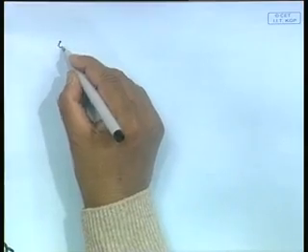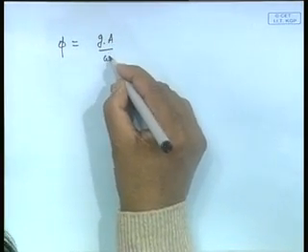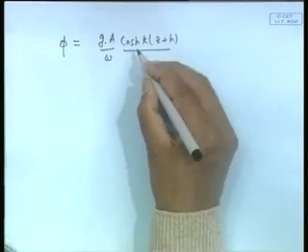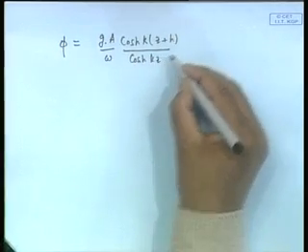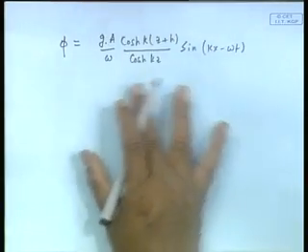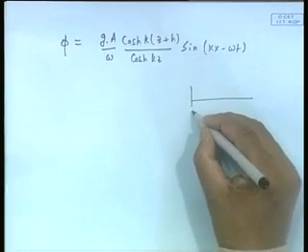Now, having gone through all this, which I will simply recapitulate, the surface gravity wave potential turns out to be, without proof, because this is supposed to have been a prerequisite to the course and you would have known that, for a linear surface gravity wave, phi equal to g a by omega times k, where this is the kind of solution that comes, let me specify these parts.